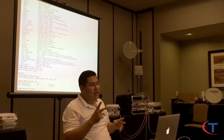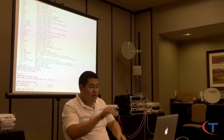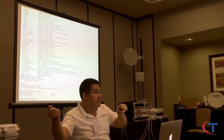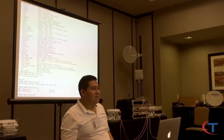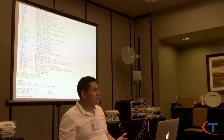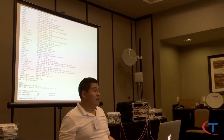What ended up being was, on our installation, we had 2 IF cable runs. One from the ODU to the actual shelter. There's a transition point there, and then another cable goes to the actual rack. The cable going from the transition point to the ODU was the problem all the time, and I was blaming the ODU. That's when we're troubleshooting with the customers. A lot of times it's, well, my IF cable looks perfect. It may look perfect, but it has water on it.